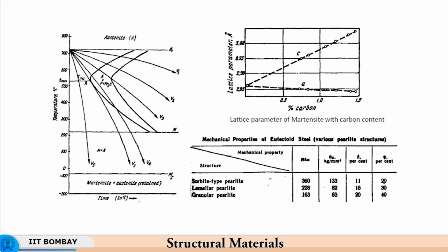So, what it means is that materials like austenitic stainless steel, for example, which has 18% chromium and 8% nickel, have a martensite start temperature much lower than the room temperature. So, at room temperature, even if you cool it fast, at whatever rate you want, it is not going to form martensite; it will still remain fully austenite. Martensite start temperature is well below the room temperature. Although this figure gives an indication that martensite start temperature is above the room temperature, that is not usually the case. It all depends on the chemical composition, degree of mechanical working, and the rate of cooling also.